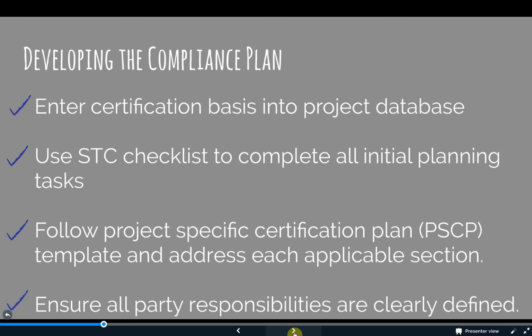This includes putting tools in place to help communicate the plan to all involved parties and to get their buy-in, to track when compliance is complete by regulation and to know when things are late or when an issue may need resolution. When developing the certification basis, the certification engineer is usually also building the compliance database that is used to identify the applicable regulations, what documents will be used as evidence for compliance, and which ODA unit members are anticipated to conduct a review and approval.